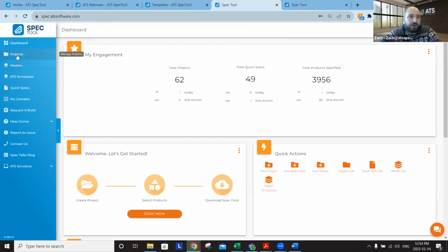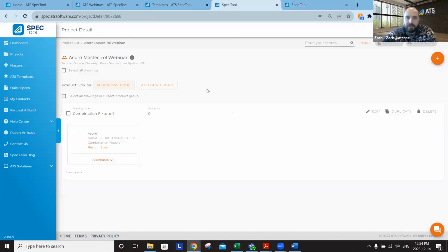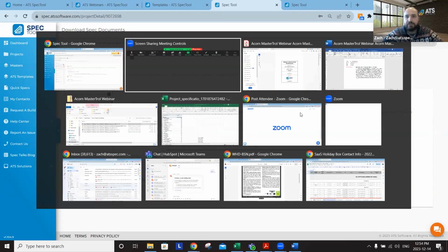And then once you are in, you can see I've created a project for the Acorn Master-Trol webinar here. I've already put a combination unit in. When I go in to access this information, all I do is click the box and hit download, and then you can download it as a submittal format, a schedule, a fixture schedule format, long spec, short spec, three-part spec for CSI, the Revit, manufacturer spec sheets, all sorts of different versions of your actual configured selection.